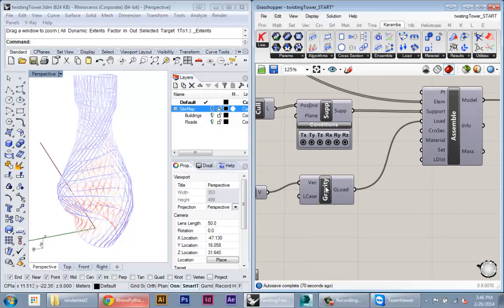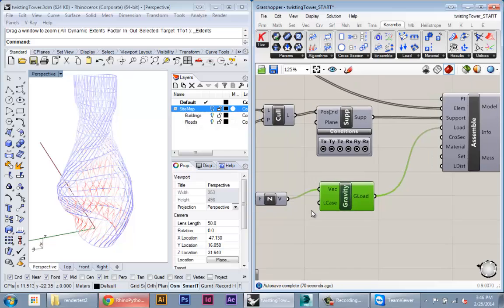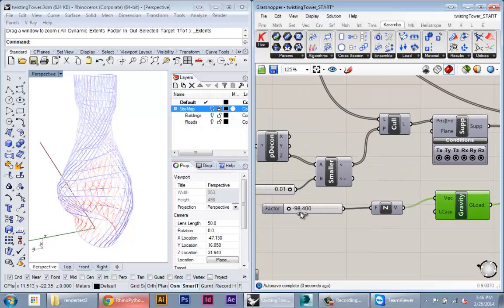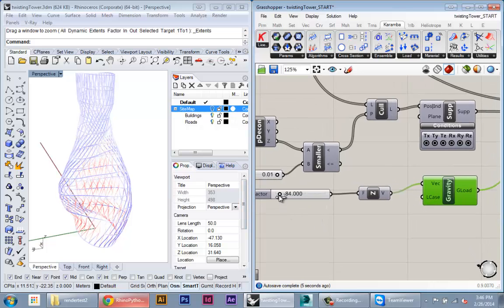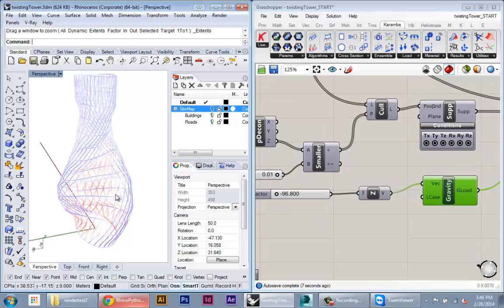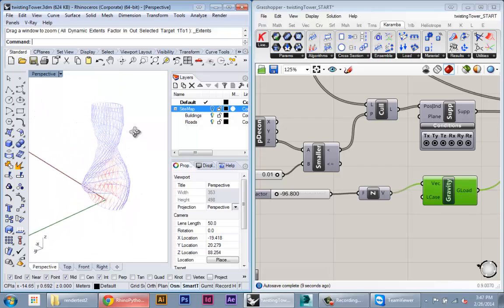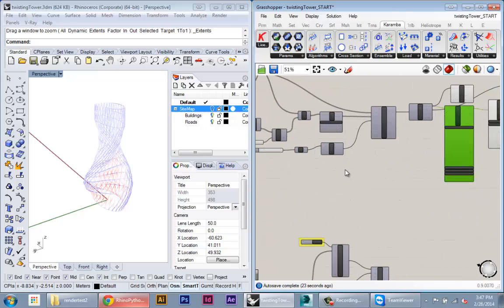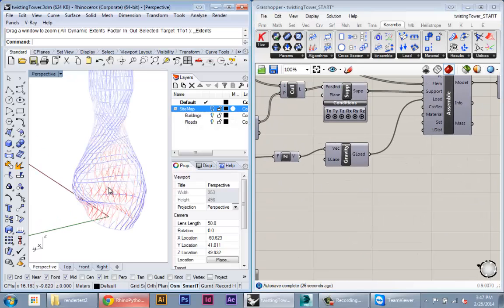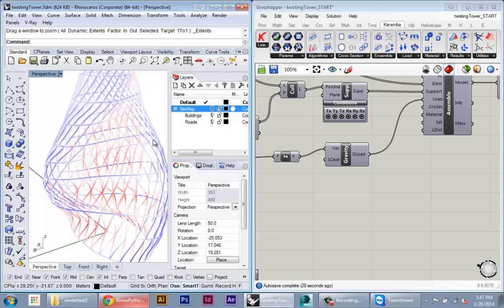Okay, so when we first did this, we created a very simple gravity load, and this will basically apply a set gravity force to each node in our model. But we might want to do something more complicated, like we might want to apply a specific load to each point, but only on one side of the model to simulate something like a wind force. This is one example, of course. You can also imagine taking all the floor plates and using only these nodes and applying a pressure to those to simulate something like a live load.